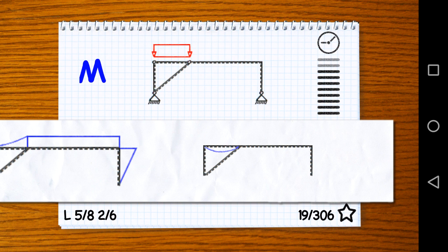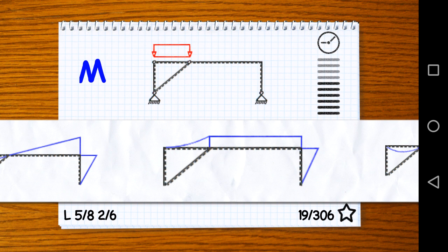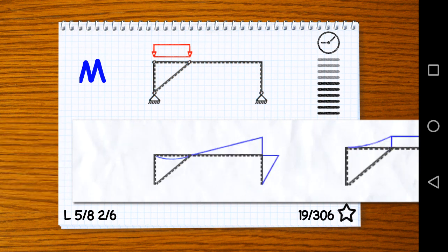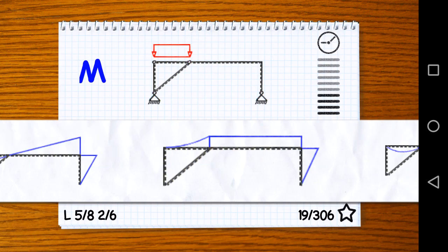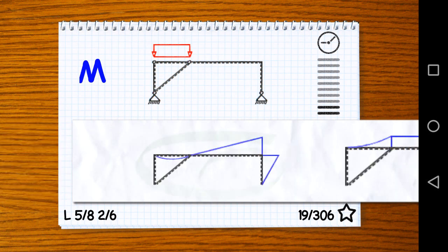Now, what about this one? We need to have the quadratic distribution on that horizontal beam. The two other elements are rods. On the left, they are rods, so they can't have any moment. Yeah, no one made that mistake. So here's our answer.